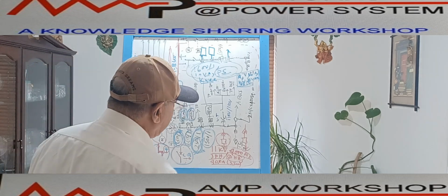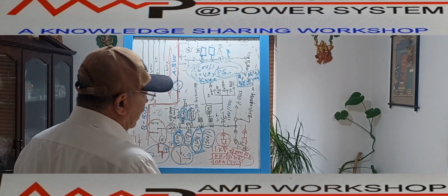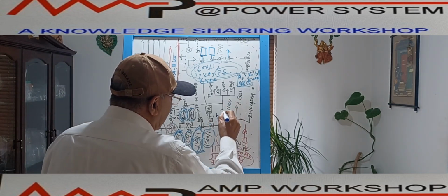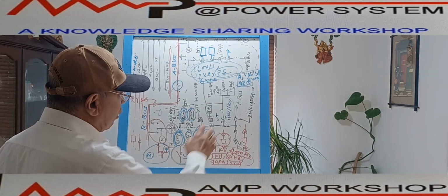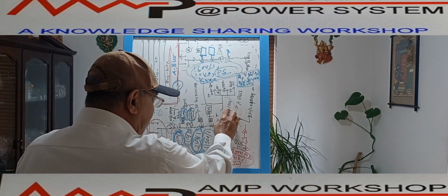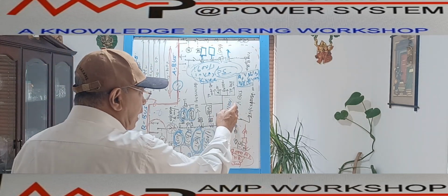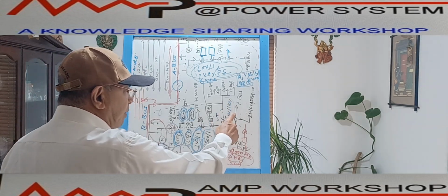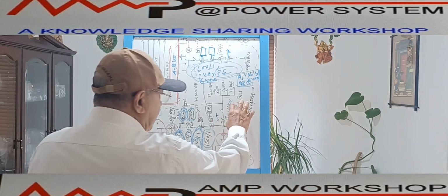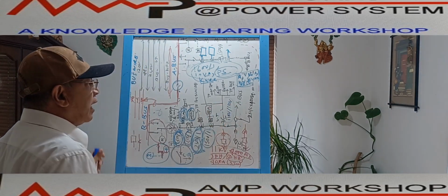So this is the line PT we have shown over here. This is an 11 kV generator. So the line PT is 11 kV by 110 volt PT. This PT also has a VA rating. It has an accuracy class. All this will come over here. What is the kVA capacity of the PT? What ratio is this, the kVA capacity, and the PS class we have to write over here. So then this PT will come over here.